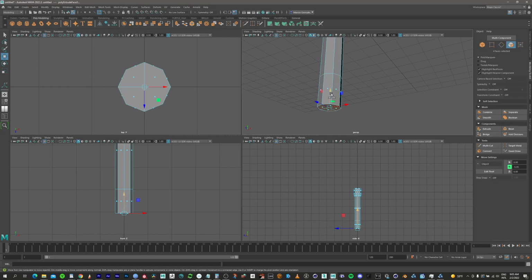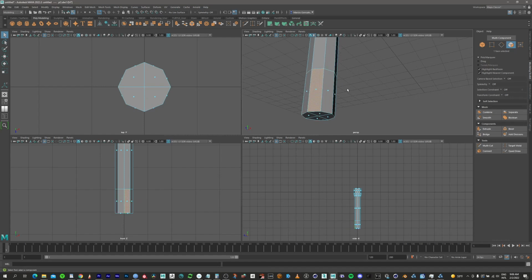If you use the extrude with the Shift, it works a little bit different. The new face will only be created when you move. So in this way, you will never create a double face that you're not aware of. So keep that in mind. Offset, click the button. If you just want to create new geometry, move with the Shift tool.